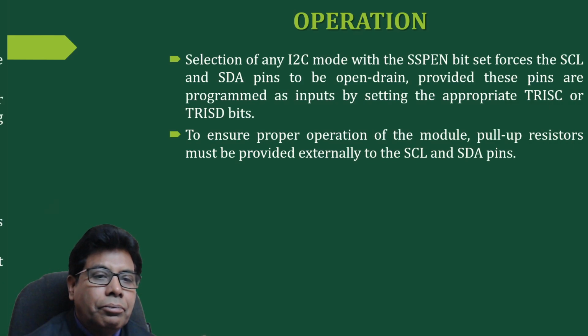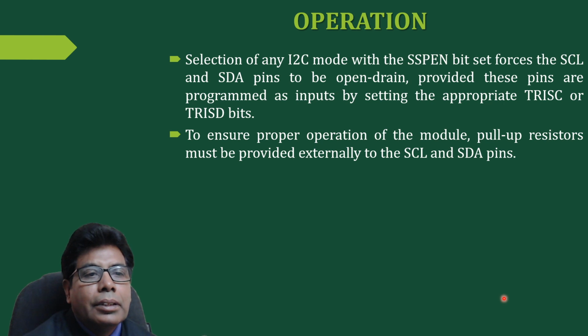Then the selection of any I2C mode with these bits will force the SCL and SDA pins to be open drain.